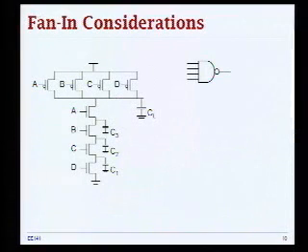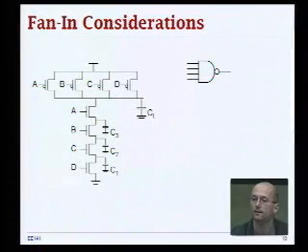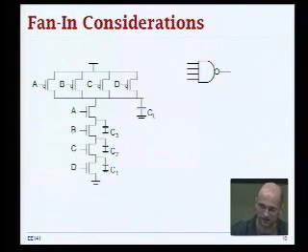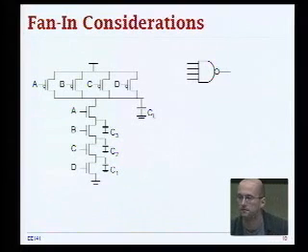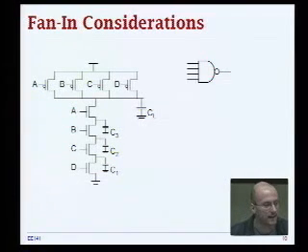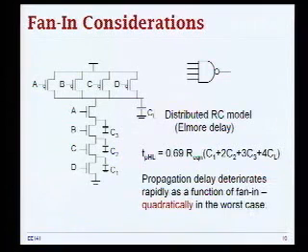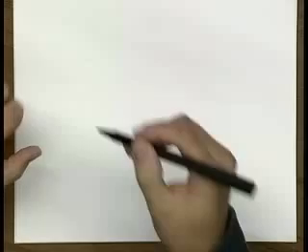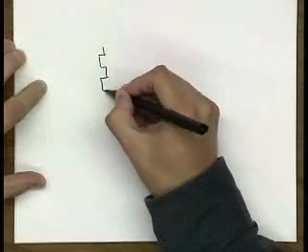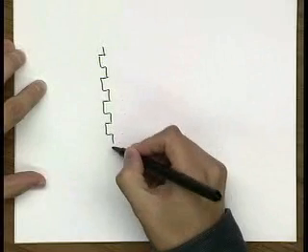Question: are you ignoring the effect of intrinsic capacitance? Correct. Yes, intrinsic capacitance is ignored for now because it was really complicated, just to get us first-hand analysis. But now we are actually coming back to your question from last lecture. So when we have a fan-in consideration over here, if we apply the Elmore delay model to this network, what is going to happen for this four input gate over here? Let's do the pull down quickly.